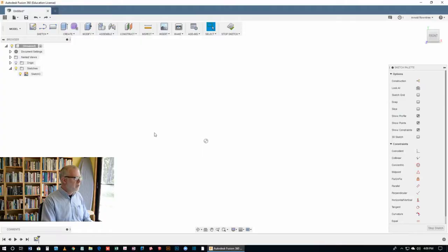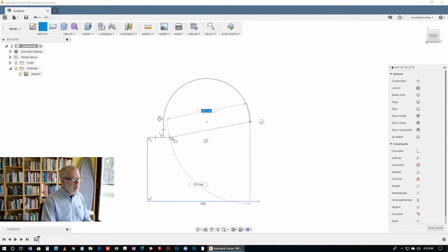So here we go with part 5. Hit the L key for the line tool and let's start drawing our sketch. I'm just looking for vertical and horizontal lines at the moment. Click and drag to get the curve, a vertical line, and you can make use of these tracking lines that come from various corners in different parts. Mouse over it to get the tracking line.